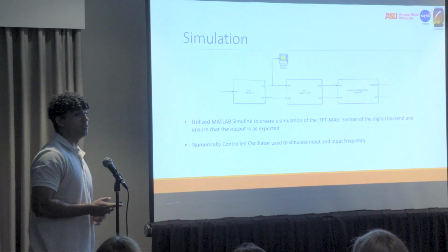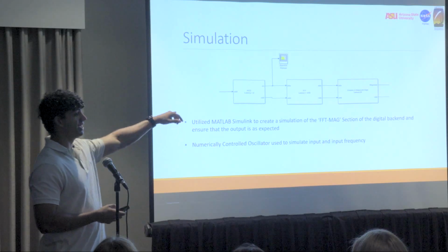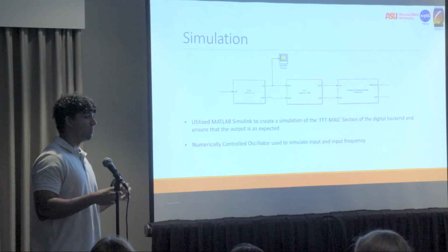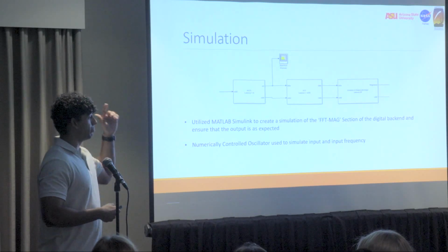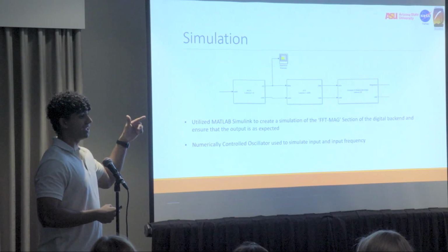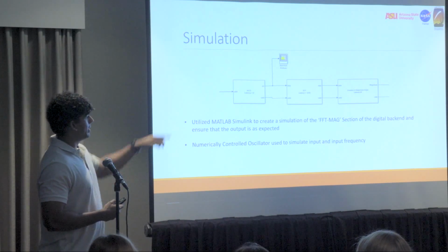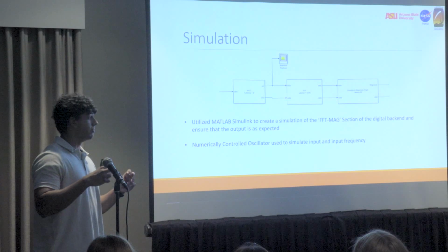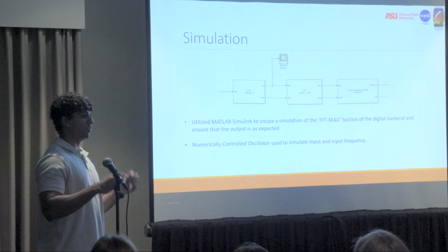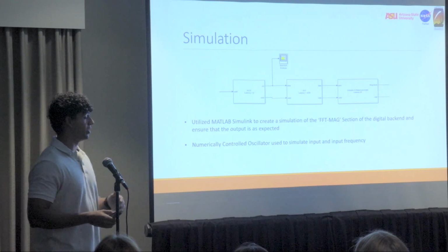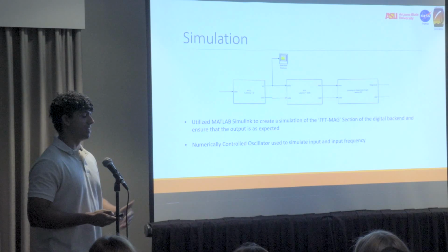So the first step is to do a simulation in MATLAB. We use an NCO, which is essentially a numerically controlled oscillator, which is a sine wave that we will be pushing through the digital backend, which is what I'm designing. And the point of this is to see if the algorithm will work correctly before we actually put it on hardware, because we don't want to waste a lot of time, as hardware is very complicated and messy.